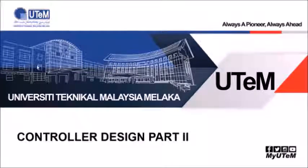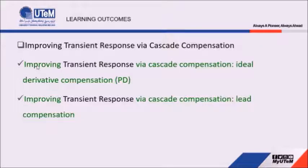Before we go further, let us look at the learning outcomes for this topic. At the end of this lecture, you should be able to understand how to improve transient response by designing the controller that we call PD controller, proportional derivative controller, also known as ideal derivative compensation. And second, use another technique that we call lead compensator, with the same objective to improve the transient response, but a different method.